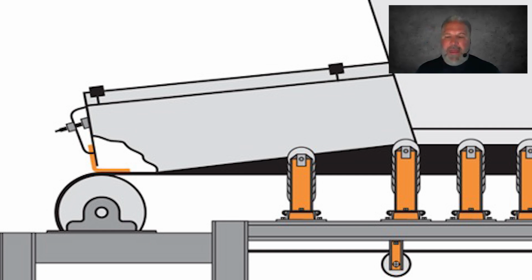So what we're recommending is that you build a tail box like you see here, built back maybe a foot, maybe 2 foot to the tail pulley. That tail pulley presents the belt at a flat surface, and it's much easier to seal the air inside this box at that flat tail pulley rather than at the trough.